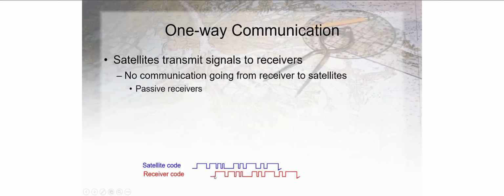And that's important because that means our receivers can do the exact same thing. So our receivers are generating this exact same code that the satellite's generating. The only difference is that the satellite, when it's generated, is 20,200 kilometers away from us, so the time of transmission is part of that difference in these two codes. So in other words, they're generated at the exact same time, but they're going to be heard at a different time. And that difference in time is actually the time of transmission.